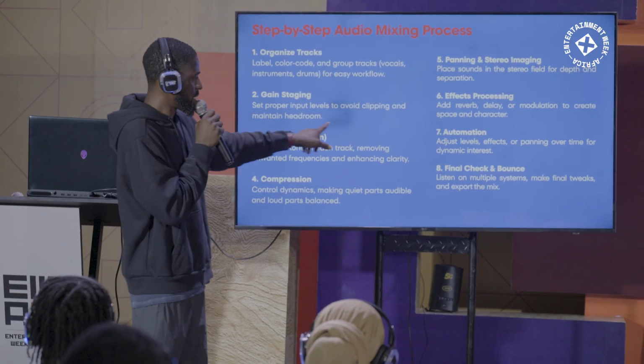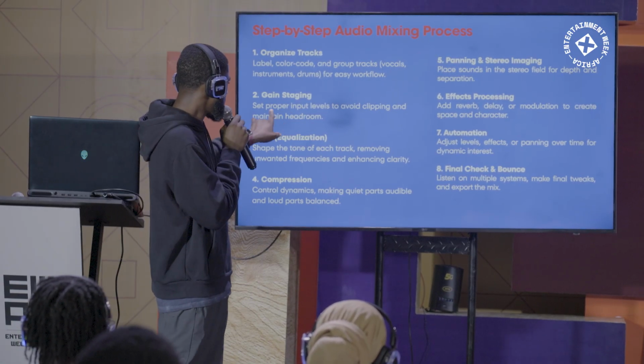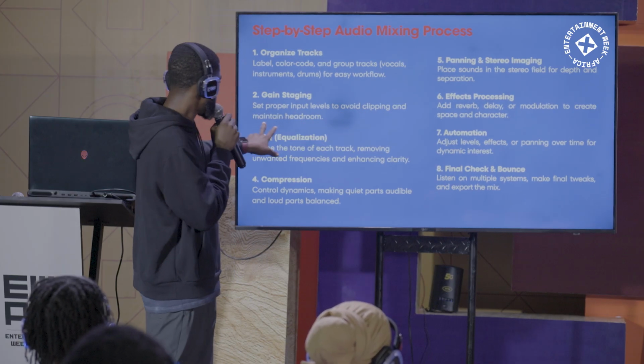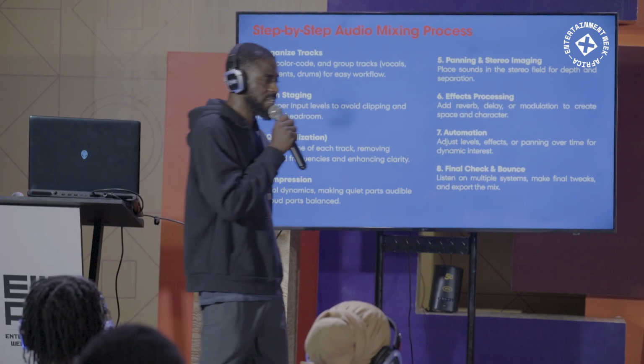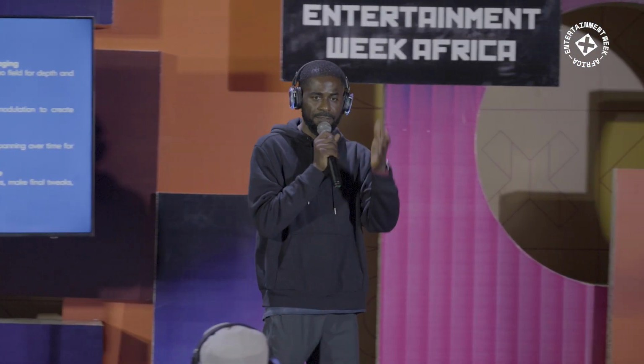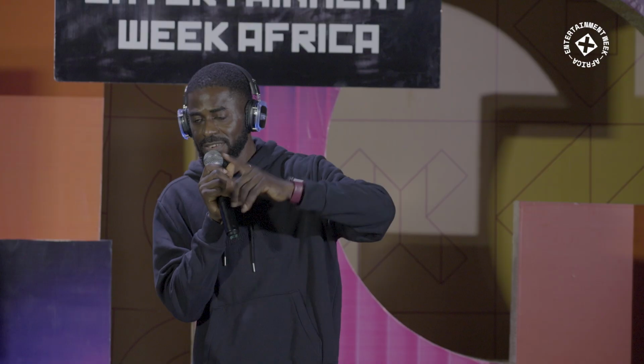Now, gain staging. Gain staging means setting a proper input level to avoid clipping and maintain headroom. I'll give you guys an illustration. A typical illustration is a traffic light. Your traffic light is green, orange, and red. Okay, let's use yellow.